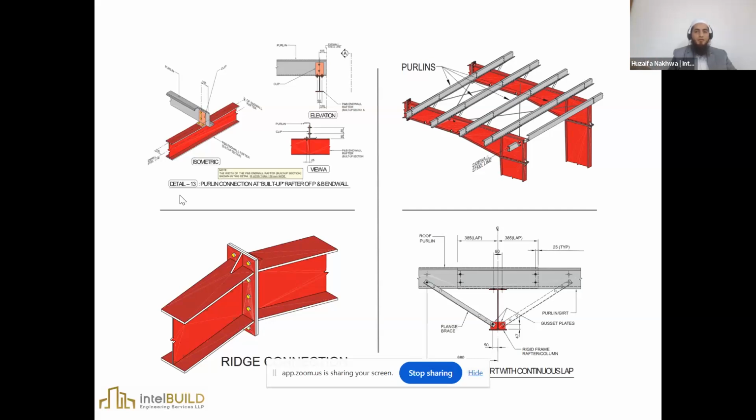So you do not have to take your welding machine to site, because everything is bolted, and every assembly is planned in such a manner that you have to design, place, and bolt every assembly properly on site by its numbers.